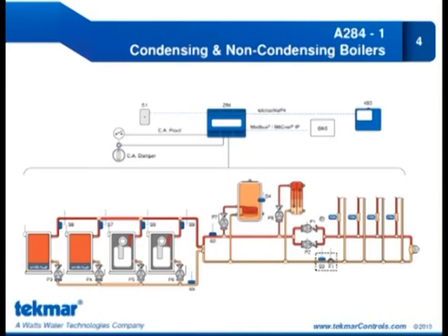Well, just to be clear, maybe I misunderstood the question, but if you look at P1 and P2, those have always been called primary pumps, right? Well, but they haven't by the industry. That's what I'm saying. What does the industry call them? Well, if you've ever been to any Bell and Gossett stuff, and maybe I'm a little unusual in that I'm a B&G guy, in this diagram, P3, 4, 5, and 6 are primary pumps, and P1 and 2 would be secondary pumps, and P7 or 8 would be zone pumps.